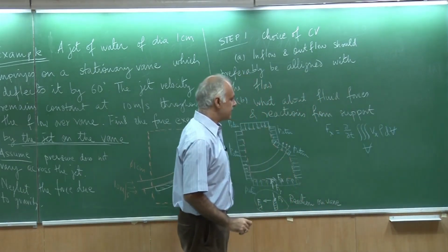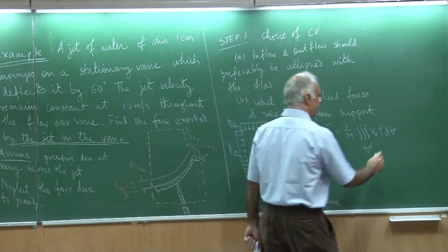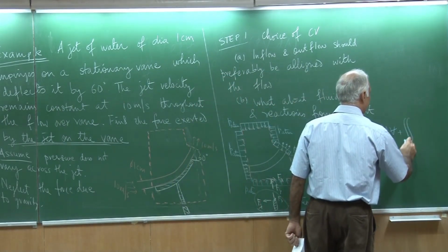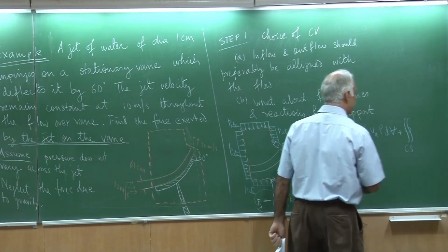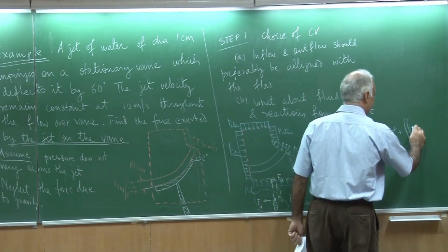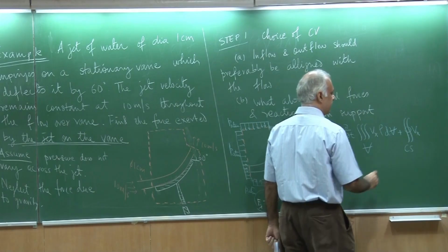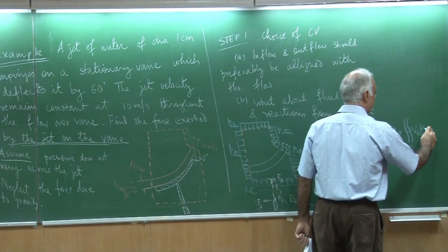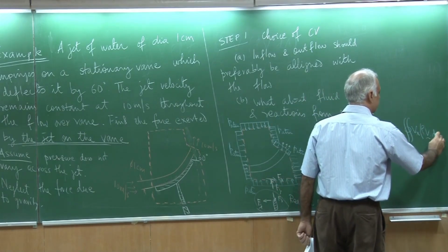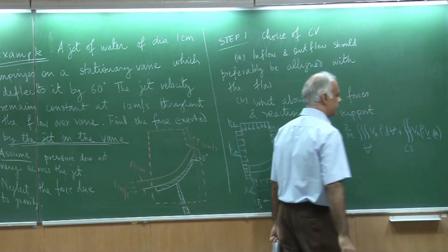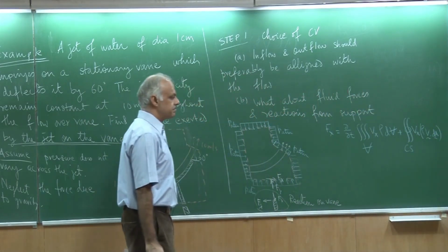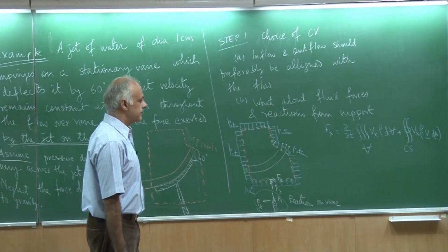Okay, so that was the unsteady term, plus I had an integral over the control surface, and I had Vx times rho V dot dA.